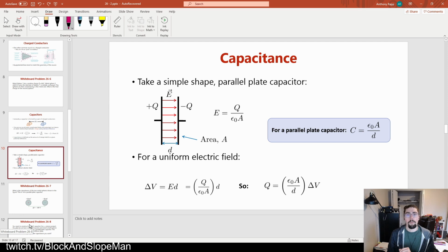But speaking of large capacitors, how do we make large capacitors? Well, there's two big factors that really are going to tell us about the capacitance of any of these parallel plate capacitors. And it's the surface area that I can pack a bunch of charge onto and the distance separating those two plates. Plates that are closer together are going to have a larger capacitance.